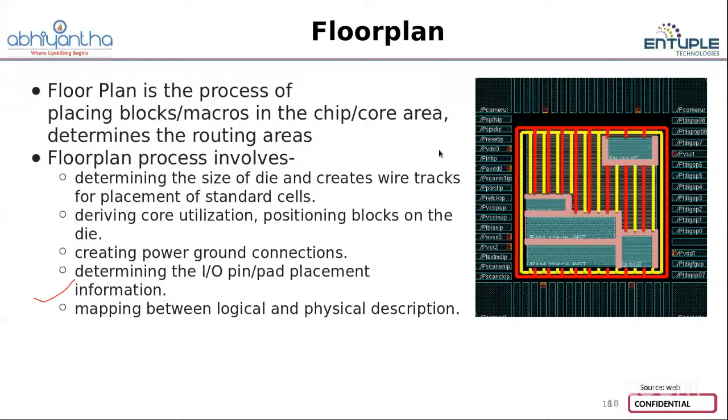In the floor plan, we need to plan the size of the IC according to the customer specification. You can do a square-based floor plan or a rectangle floor plan. The rectangle depends on the area and width of the design. The area and width can keep changing your floor plan size. Once all these steps are over, we go to the next step.